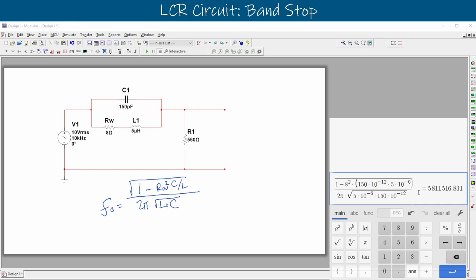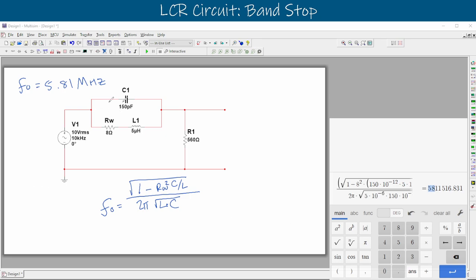And we've got 5.8 megahertz, 5.81 megahertz. And we'll write that down. We'll say that our FO is equal to 5.81 megahertz. We know that's megahertz because of how forward we can move our decimal point. Our decimal point's way back here right now. We can go forward 1, 2, 3 spots there, and another 3 spots, and put our decimal point right in front of that 5, and between the 5 and the 8 there, and that gave us that mega, times 10 to the positive 6 location.